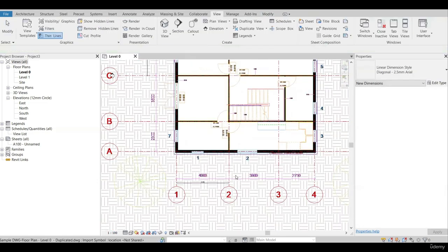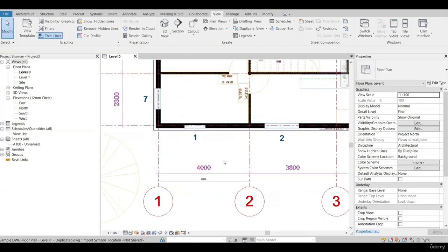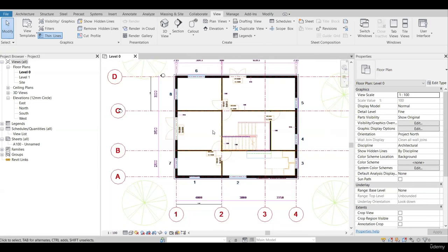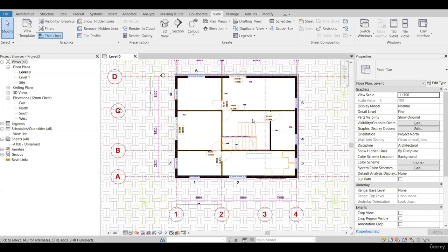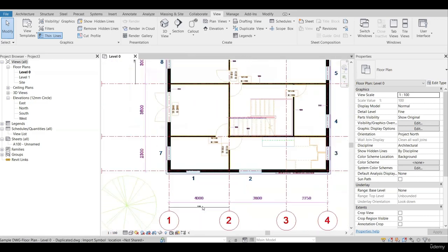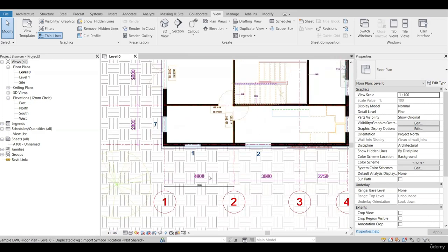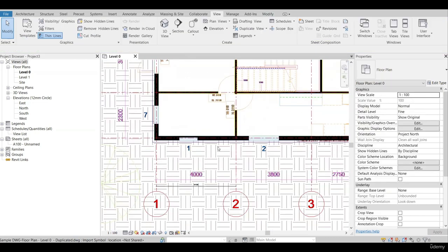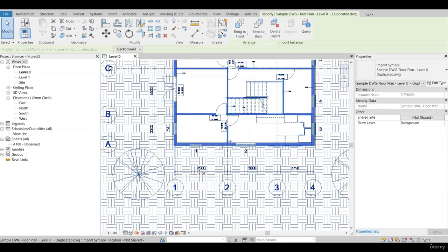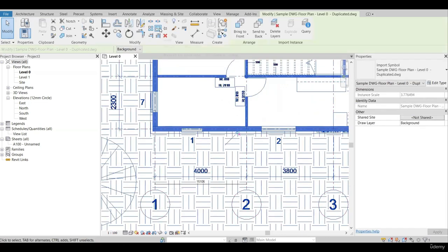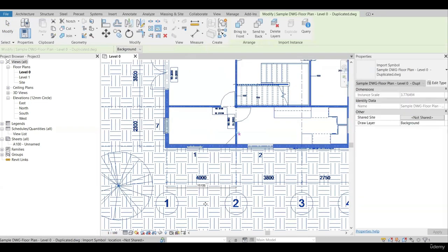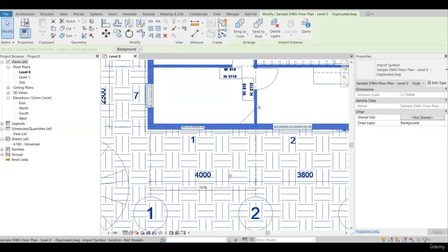As we have checked it, we can comment it as an incorrect scale, because the imported or the linked data has a change in scale which is not exactly representing it. In order to change the scale or maintain the scale correct, we need to rescale the link data. To do that, select the link, go to Scale, and make sure you have the correct dimensions of the 2 points that you are selecting for scaling.